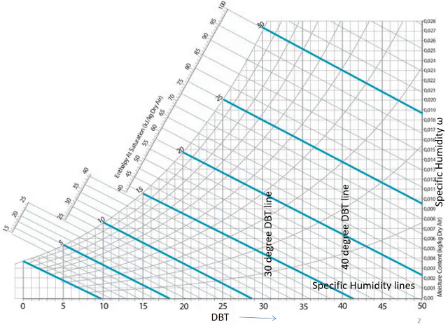Now moving further, you see the saturation line, that curve. That is called the saturation line. Here the relative humidity is 100%. That means this line represents the saturated air condition. What is saturated air? Air is said to be saturated when the partial pressure of water vapor in the air is equal to the saturation pressure at the given temperature. Then air is called saturated. So this line indicates the saturation line.